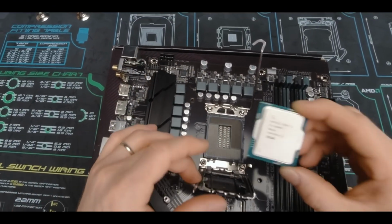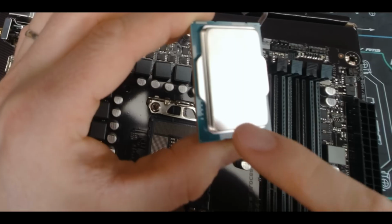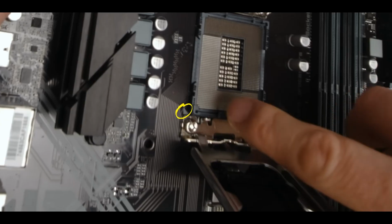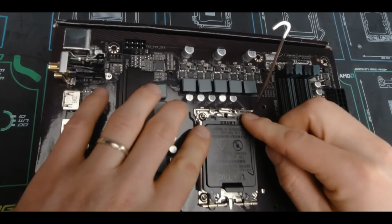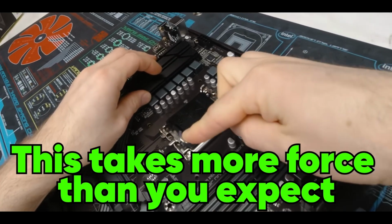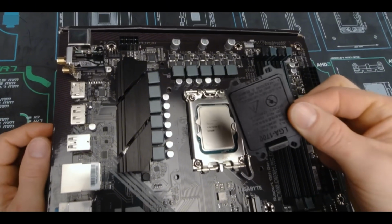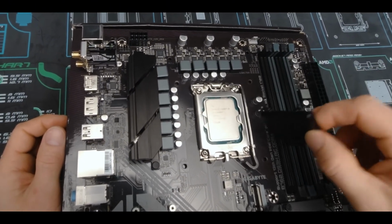You want to first open up the CPU socket by lifting the metal lever and frame. Then align the small triangle on the corner of the CPU with the small triangle on the socket and gently place the CPU into the socket. Once it's in place, close the lever to secure it. Make sure before you close the lever you don't push down on the CPU because this could damage the pins.